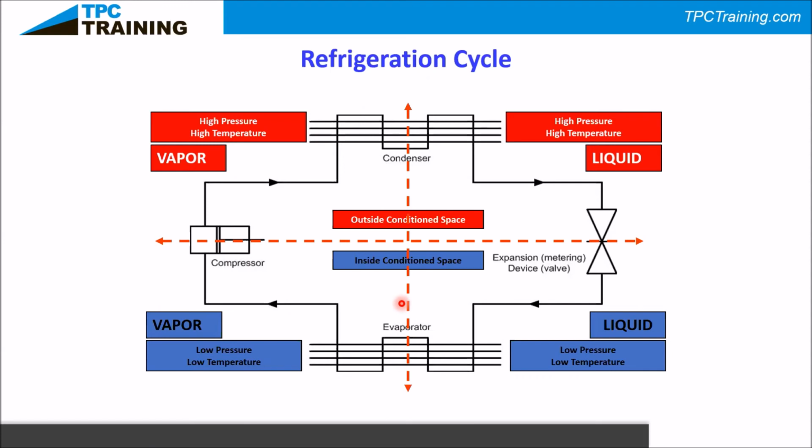If anyone has a car and knows they're in salt water all the time, it starts deteriorating the metals. So it'll cause your unit to leak faster because it's going to deteriorate the coil, but the refrigeration cycle itself wouldn't be as affected by it. Ah, gotcha. That's a good point because that salt can really break down all sorts of electrical or mechanical equipment over time for sure.